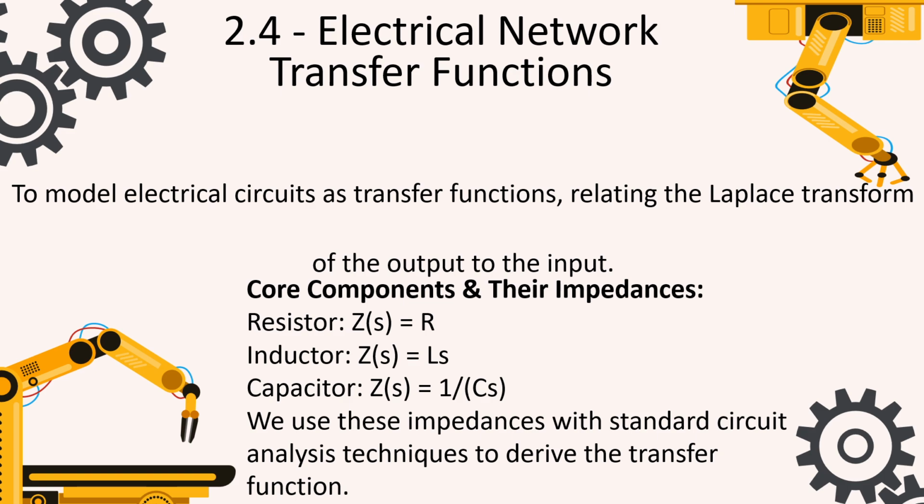As you can see, a resistor's impedance is simply its resistance R, an inductor's impedance is Ls, and the capacitor's impedance is 1 over Cs. By using these impedance values, we can apply standard circuit analysis techniques to derive the overall transfer functions of a network.